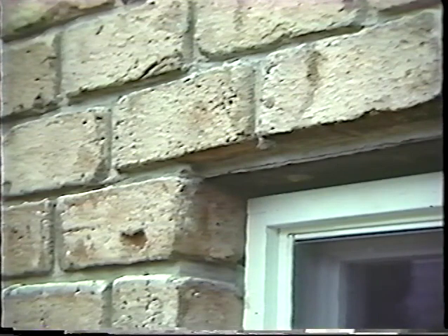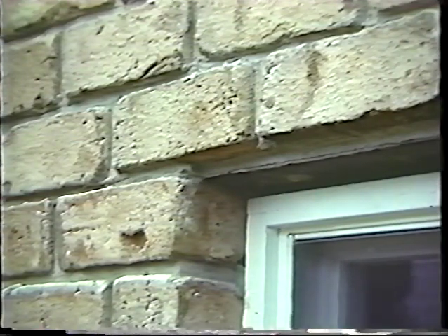Brick should never be supported on mortar built up on the outside of the foundation, nor on insulation, nor on 2x4s or other non-rigid support. The same bearing rules apply for bearing on lintels and other means of support. At least 2/3 of the brick thickness must rest on the horizontal leg of the lintel.